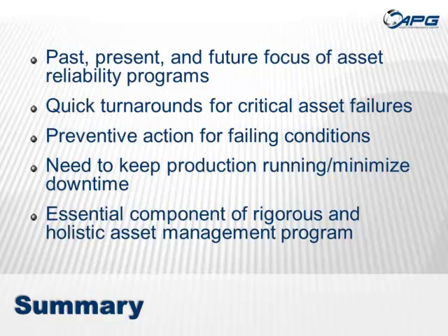The use that it can take for addressing future issues is to identify new failure modes that we can build into our forward-looking asset management practices, such as RCM, to build more robust preventive actions around this new failure mode that's discovered from RCFA.